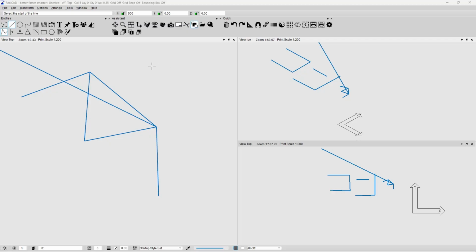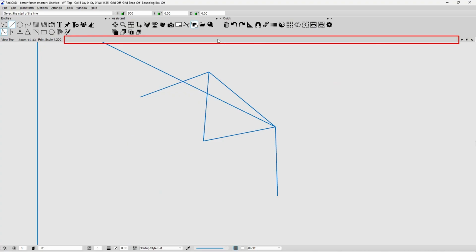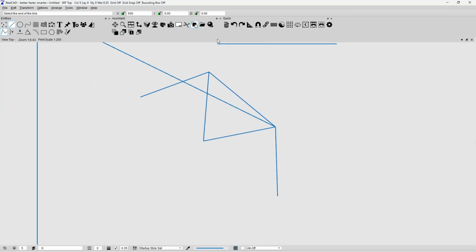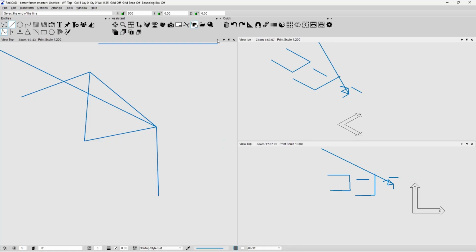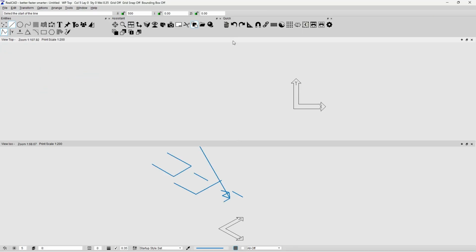When you have a split screen, you can maximize any one of those screens by selecting this button here, or by double-clicking on the area at the top of the view, and it will switch between either being a full screen or a tiled view. If they get lost, or you get lost for any reason, come up to the word Window and select Tile, and it will refresh the screen into these tiled elements. You can switch off any one of them by clicking on this cross.